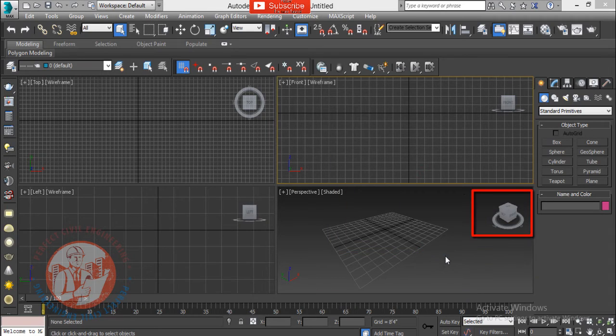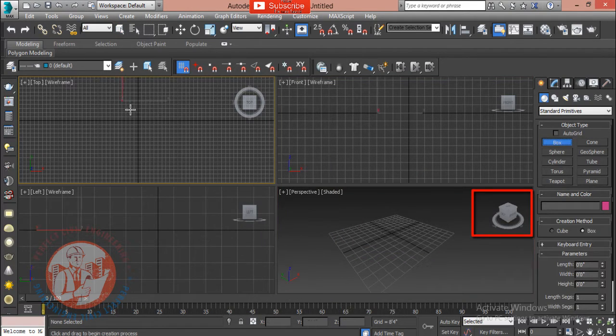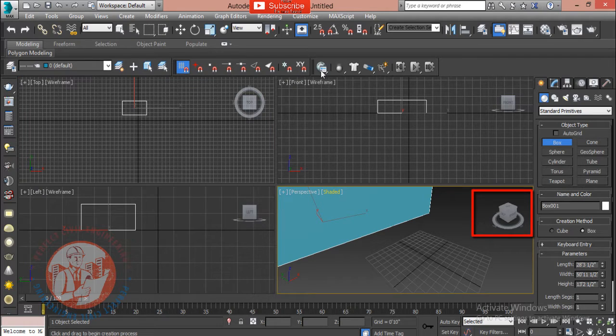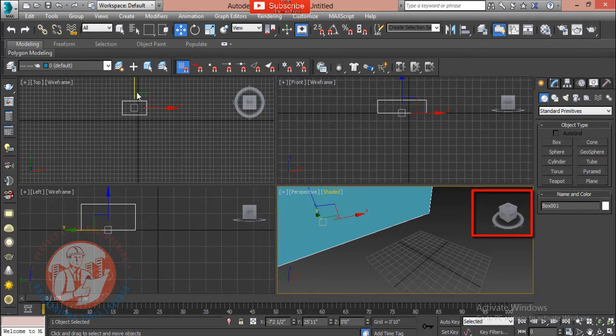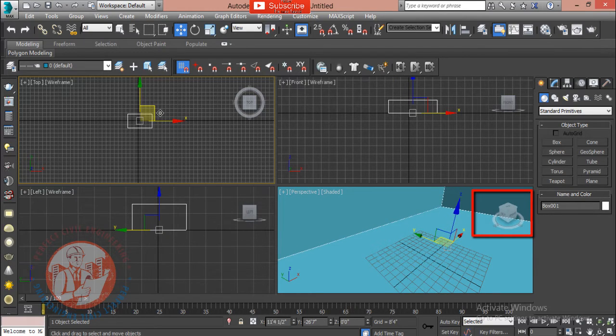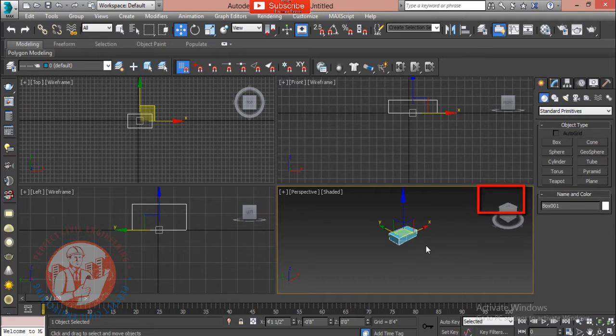Working with the ViewCube. The ViewCube consists of a 3D cube that is labeled on each side and centered in a ring located on the ground plane. Its purpose is to show the current orientation of the viewport, but it is also interactive and provides a way to quickly move among the different views. The ViewCube lets you quickly change the current view.